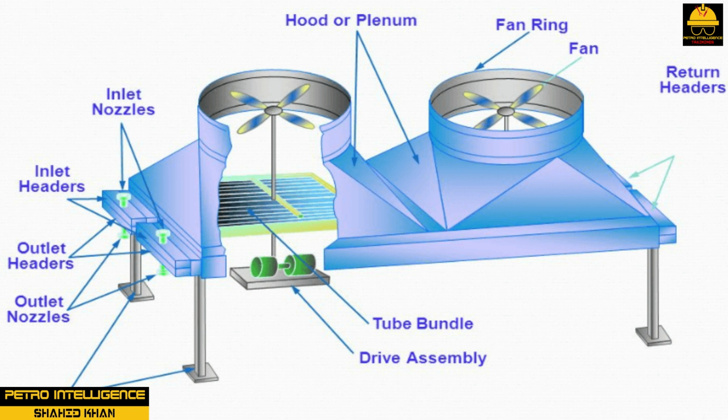Air-cooled heat exchangers do not require the use of a shell in operation. Process tubes are connected to an inlet and a return header box. The tubes can be finned or plain. A fan is used to push or pull outside air over the exposed tubes. Air-cooled heat exchangers are primarily used in condensing operations where a high level of heat transfer is required.